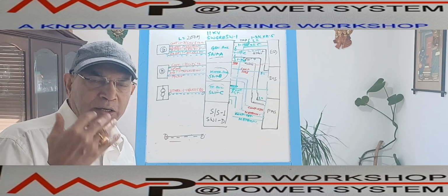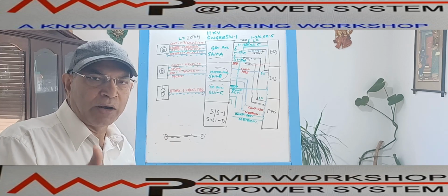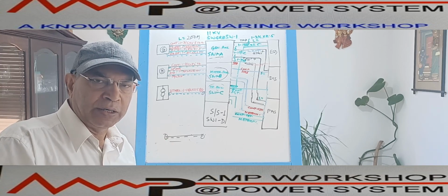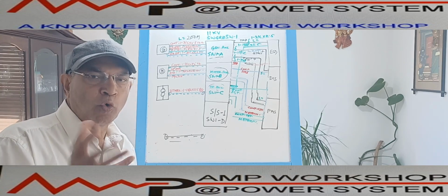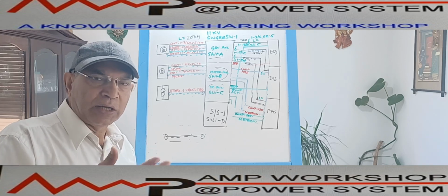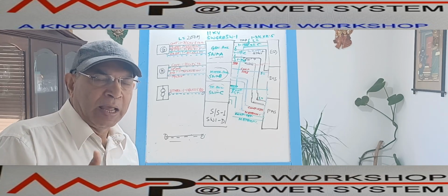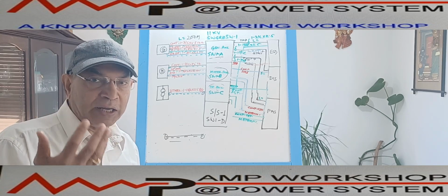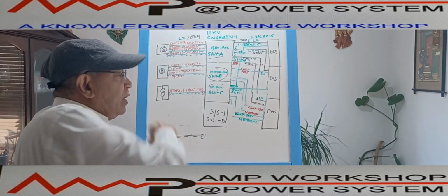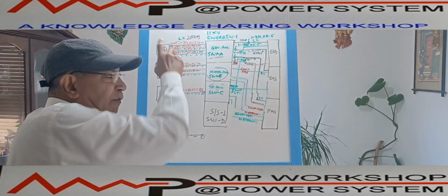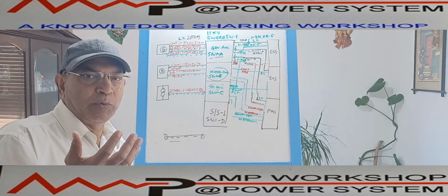In the control room, there is a control panel or DCS from where we can open and close the circuit breaker. Similarly, there is a power management system from where we can also open and close the circuit breaker. So that is another control, the PMS. And then we have seen, in case of fire and gas, where the switchgear or this generator is located, in that area, if there is a fire, then the fire and gas system will operate.